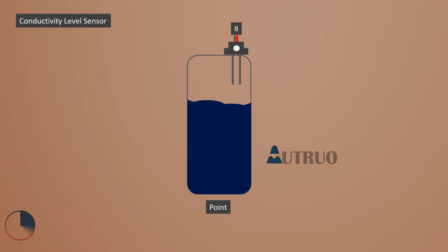In sensor B, the reverse is the case. The tank is not needed to complete the circuit. The ions in the solution bridge the two probes together once both probes touch the liquid. One of the probes will be negatively charged, and the ions in the solution will help transfer the ions to the second probe. Unlike the first setup where the tank grounding coupled with liquid rise activates the single sensor probe, the second setup uses a combination of the probes and liquid rise but not the tank grounding.